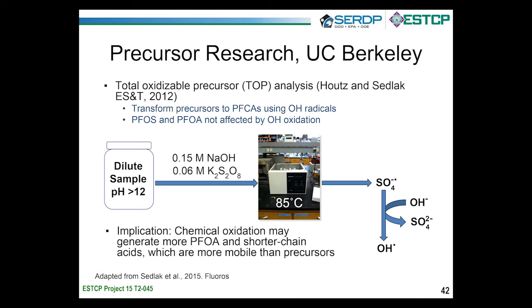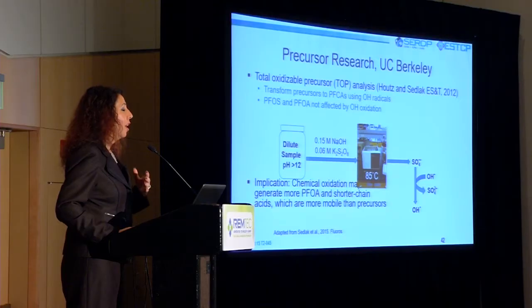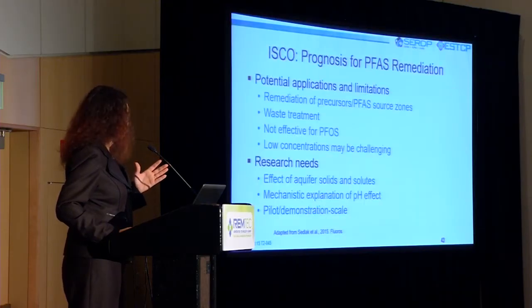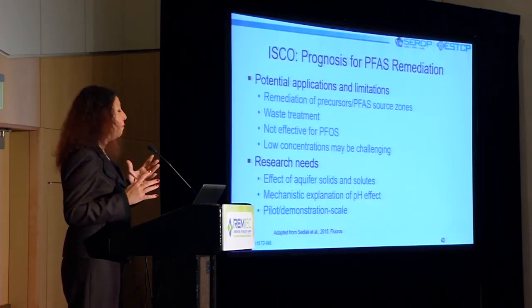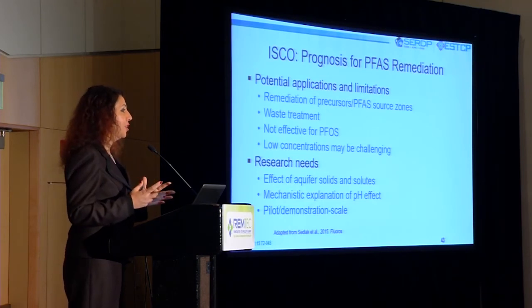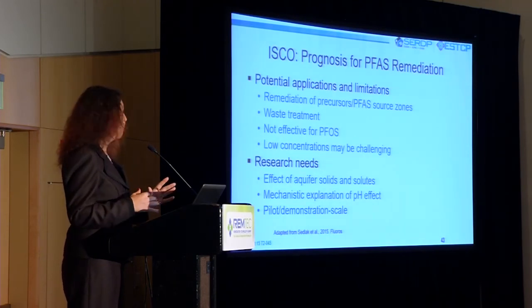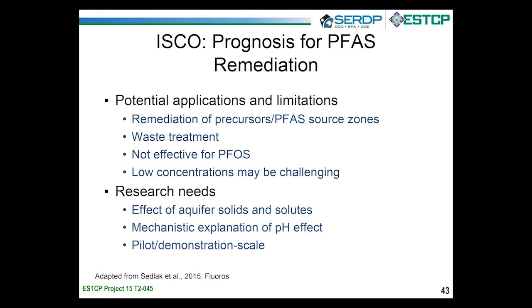And what I want to leave you with here, again, is a word of caution that our understanding of in situ chemical oxidation right now is very preliminary. The work that's been done at the laboratory scale is promising for PFOA, but is not really very effective for PFOS. So any design approach involving a field implementation has to account for the precursor issue.